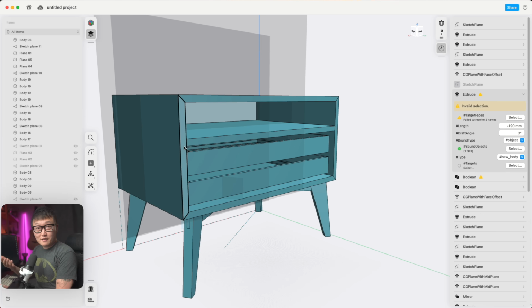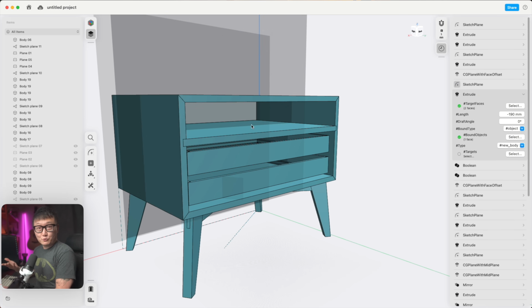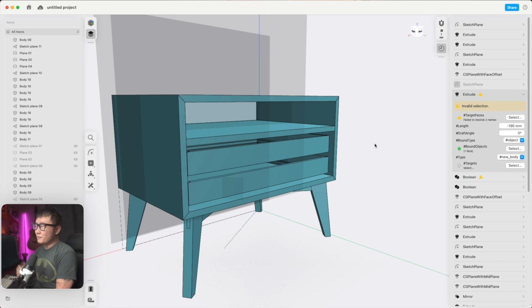And let's say that our client came to us with a late change. And we made this change and gave them a new quote. And they're like, oh, no, never mind, this costs too much. And so we can just come over here, suppress it and go back to this original design without deleting anything. And then say after an hour, they come back and say, never mind, I really like that new design. I got the funding for it. Let's move forward. Then we can just come over here and bring everything back like that without needing to go back and remodel anything.